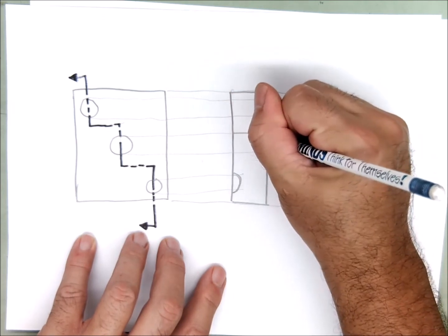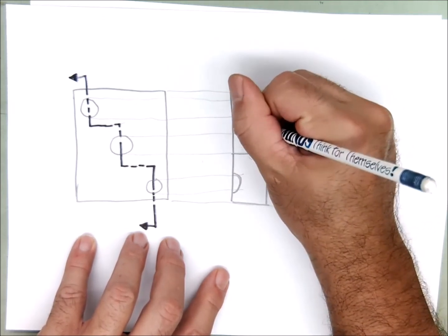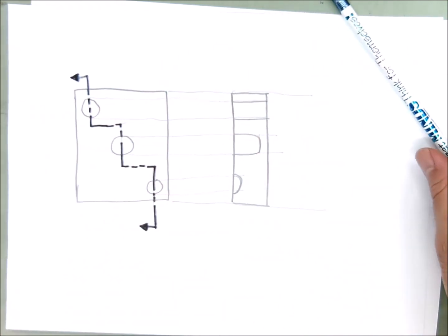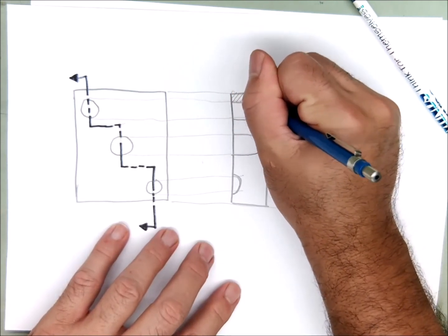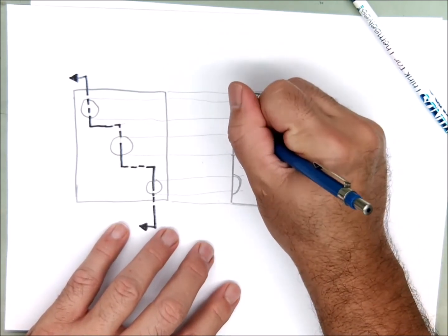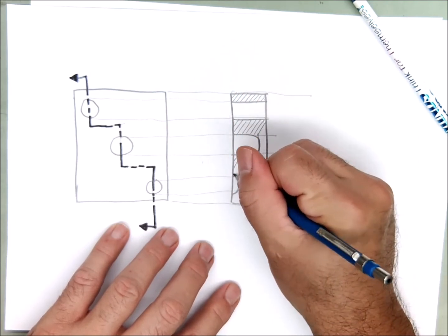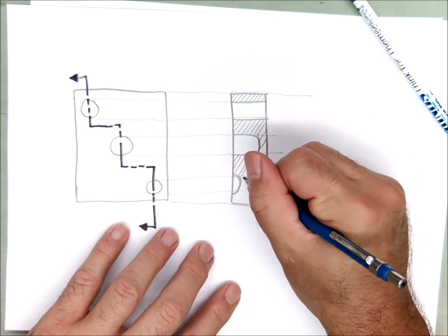And now what I got is I have 1 drawing that shows all 3 conditions here as sections. And I didn't have to make 3 drawings and 3 cutting plane lines and miles of section lines. So hey, that's a win for me. That's a time saver.